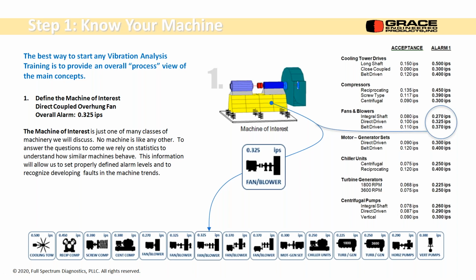They're all going to have their own alarm criteria. The nice thing about having these real-time sensors that are bolted in place or magnet mounted in place is that they'll continuously take data, and any subtle change from the mean level is going to be recorded. As I mentioned on Tuesday, the alarm levels are the mean level plus 3 sigma.